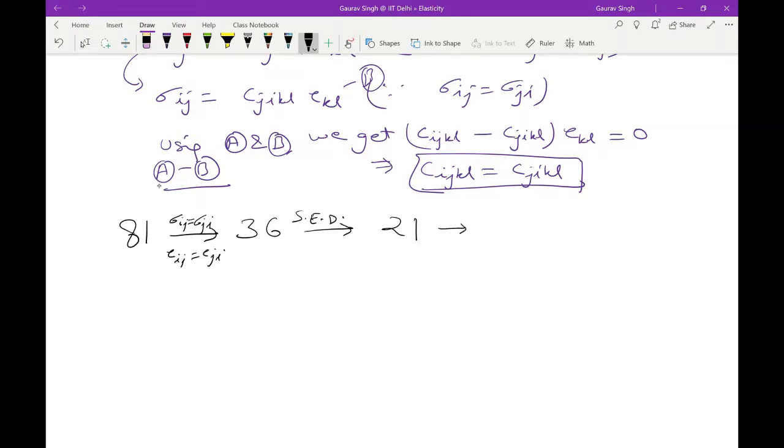And this will move on to some other reductions before being told that for an isotropic solid, and I'll tell you the meaning of isotropy in a moment, you will have only two independent constants in the elasticity tensor. Okay, so this will come out in more detail when we study anisotropic elasticity, but for now you should remember that an isotropic solid, if following linear elasticity, will have only two independent constants.